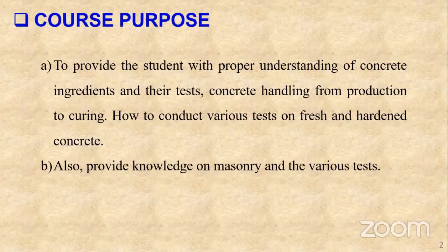Quality control is very key, because concrete is usually produced on site, and not everyone is an expert in concrete. Some people handle concrete out of experience. You encounter a mason, a fundi, and he says, we have been doing this for so long. Maybe he had just been exposed to small buildings, but now you are talking of maybe a high-rise building, and he still won't use the concrete the way he knew about, or the way he has understood through experience. That's why, although it is not the only cause of collapse of buildings in Kenya, material quality control is one of the major problems. Of course, there are other issues like foundation settlement, and so on, but quality control.